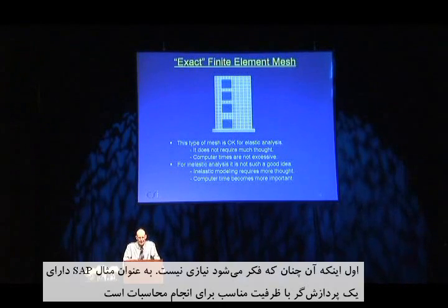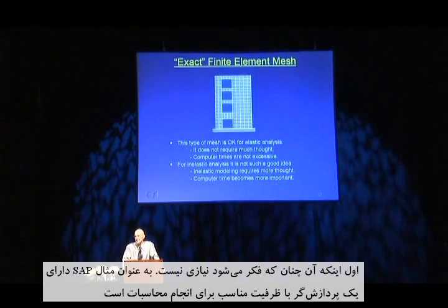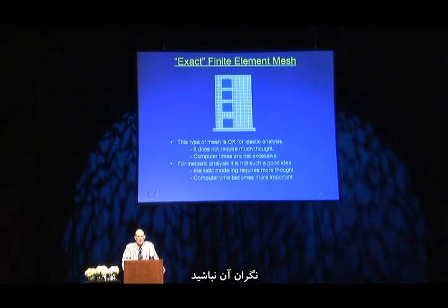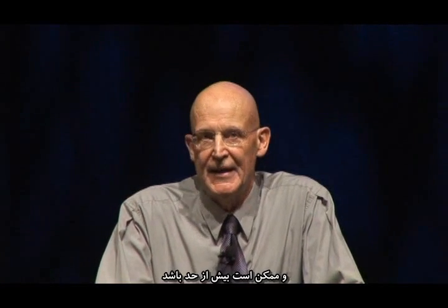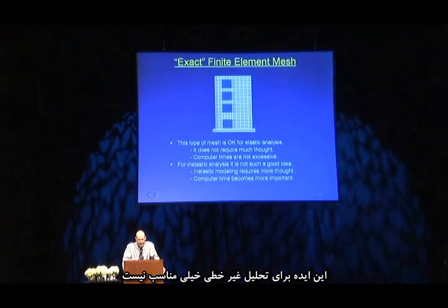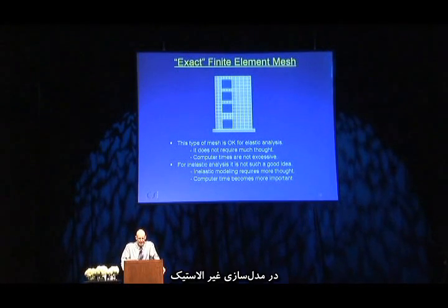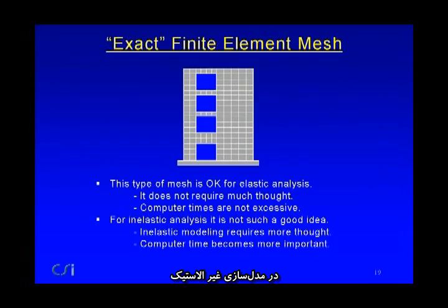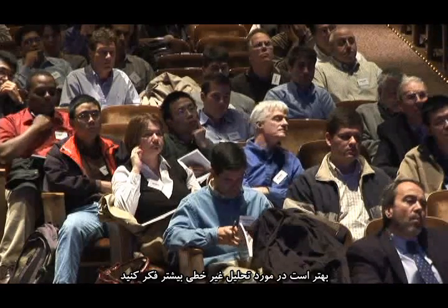Firstly, it doesn't require much thought. And SAP, for example, has got very nice meshing capabilities that will do the job for you. You don't have to worry about it. And if you're doing a linear analysis, the computer times aren't very great, so it may be overkill, but it doesn't really matter very much. Now, for inelastic analysis, this isn't such a good idea. Inelastic modeling requires a lot more thought. It's okay if you're doing elastic analysis. Yeah, there's lots of elements. We don't have to think about it. Non-linear analysis, you'd better think about it.